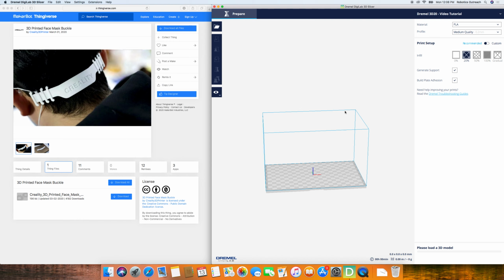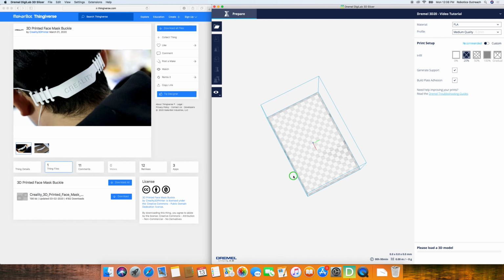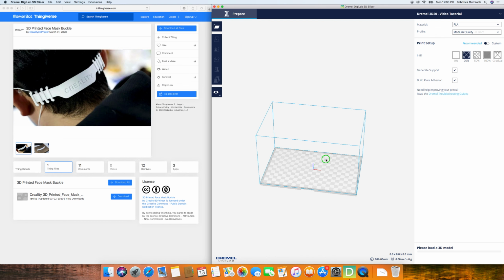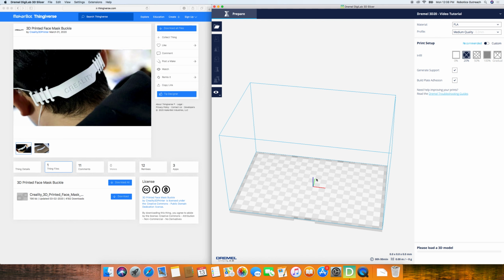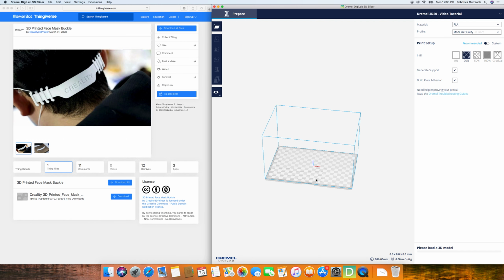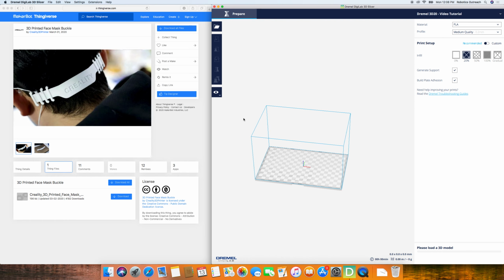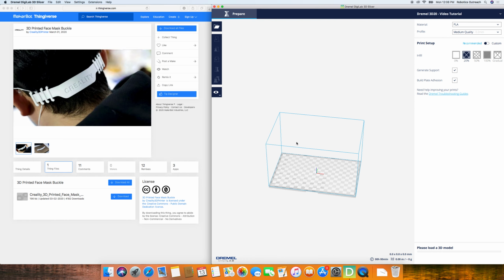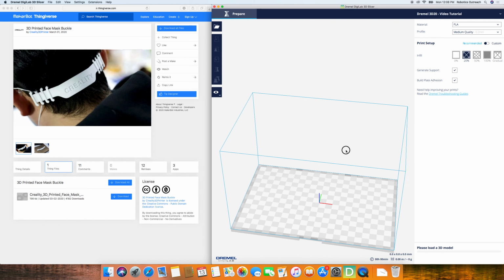So to rotate my perspective, I'm actually going to click the right click button on my mouse, and you can see that I can right click really nicely. If I want to zoom in, just like zooming and scrolling on a page, use the scroll wheel. Now, if I want to pan, I'm going to hold down the scroll wheel and just move back and forth. Now, to select, I just click with my left click button.